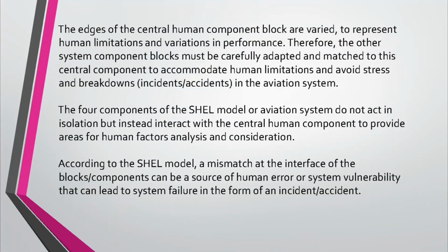As we have seen earlier in the diagram, the edges of the blocks are irregular, which represents the limitations of different components. The SHELL model says that different components must match with the central liveware block in order to prevent any incident or accident. We cannot alter the human beings, but we can alter the other components so that they adapt to the liveware. A mismatch between liveware and other components can lead to an incident or accident.